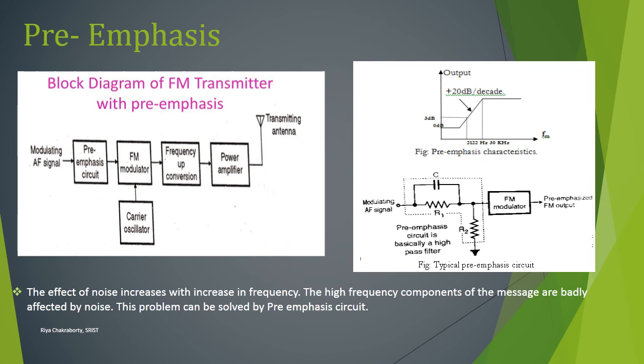So, the artificial boosting of higher modulating frequencies, remember, is called pre-emphasis. So, there is a pre-emphasis circuit. Boosting of higher frequency modulating signal is achieved by this circuit.